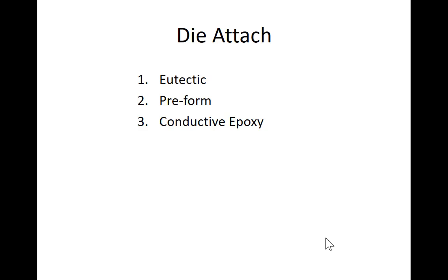You've got to melt solder, you heat it up. So I'm going to look at this face here. When you heat it up, I'm going to exaggerate, it's going to look like a pillow. Does that make sense? You heat it up, and as it expands, the device no longer stays rectangular.